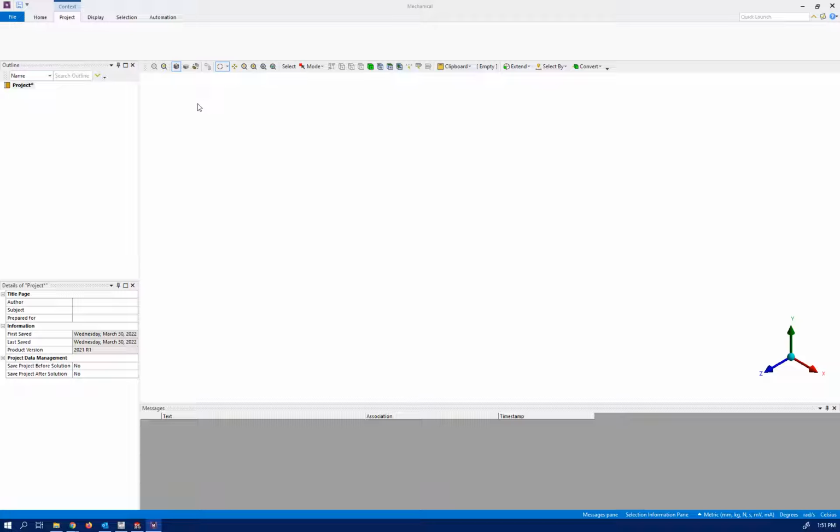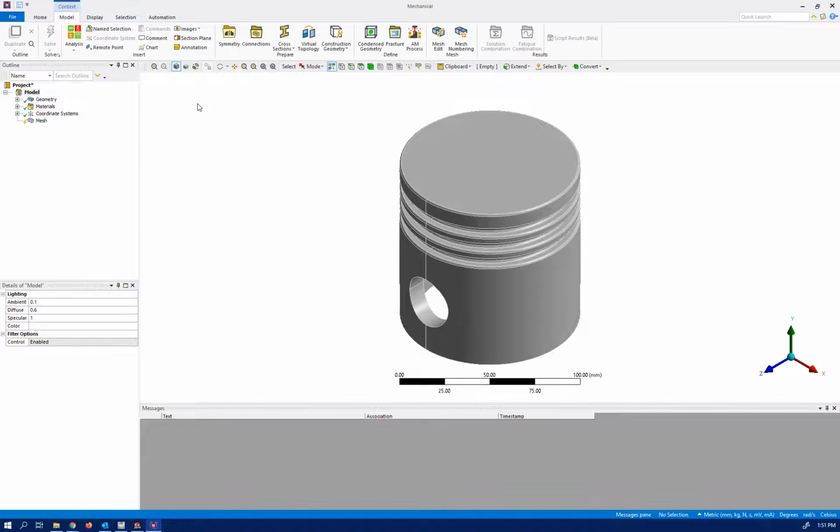So I'm just going to randomly select the temperature for the top, and then this piston should cool down, otherwise the temperature just rises and destroys the piston. So from the sides of the piston we should cool it down. So I'm going to apply some cooling effect for the sides. Okay.